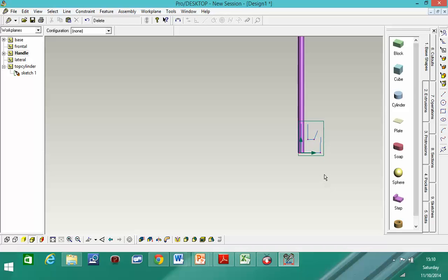Alright, for some reason I've decided to modify the whole handle. Okay, just click on the line and say delete, and this will just happen. All right, I'll just complete this side with what I've got here. Let's complete this so we can have a closed figure.